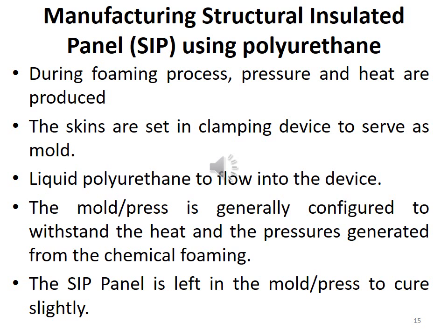The skins must be held apart from each other to allow the liquid polyurethane material to flow into the device. Once in the device, the foam begins to rise.